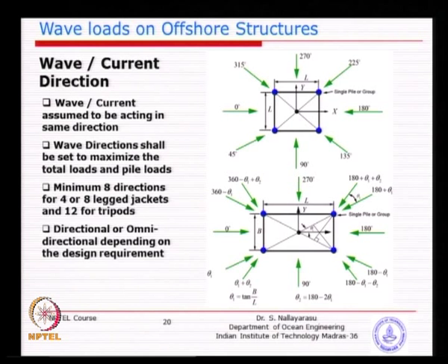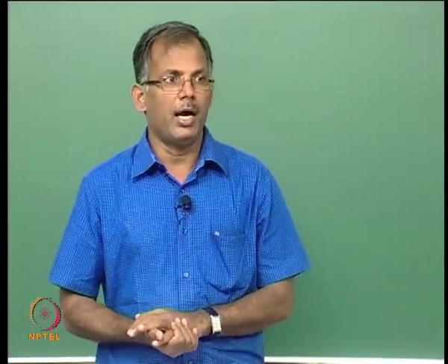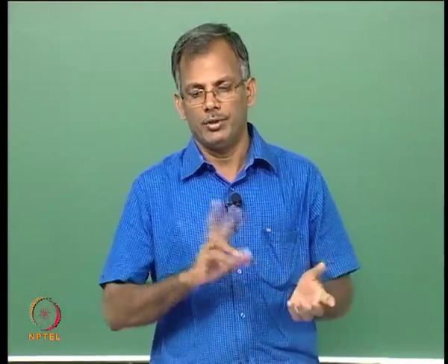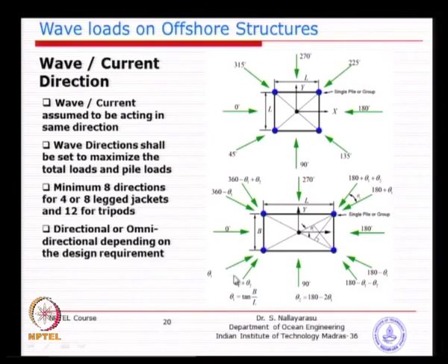And the next one is the selection of wave direction, which I think is as important as what we are trying to do using estimation, basically maximizing the loads on the structures. The other day we were discussing that the diagonal direction could prove to be the most effective, and higher forces could be produced because of the decoupling effect. So, several times we also ask for a variation: instead of only doing diagonal, you could do plus minus 5 degrees, plus minus 10 degrees, depending upon uncertainty at the site.